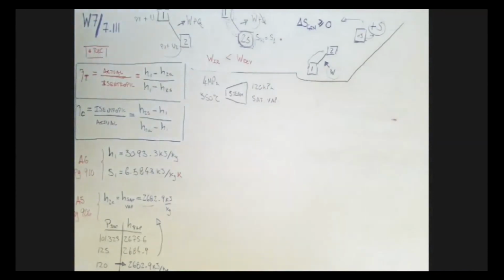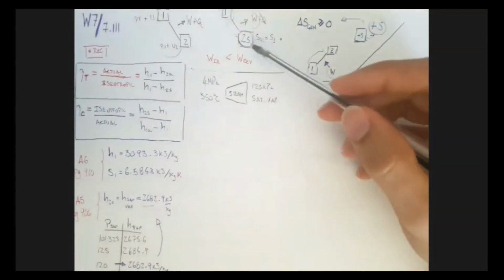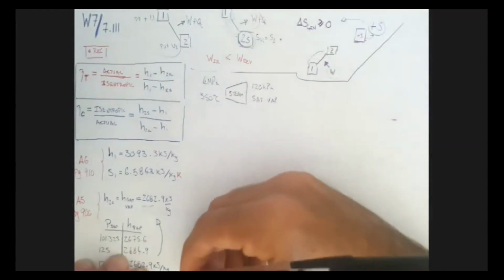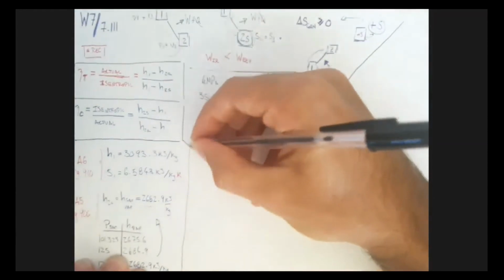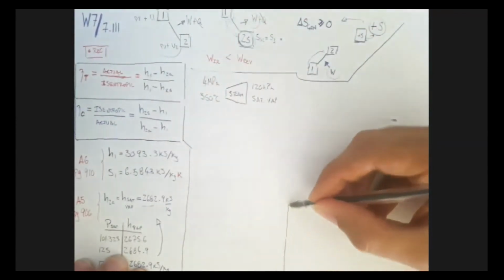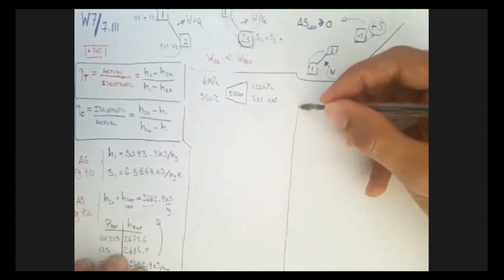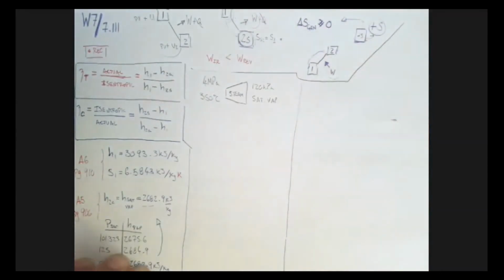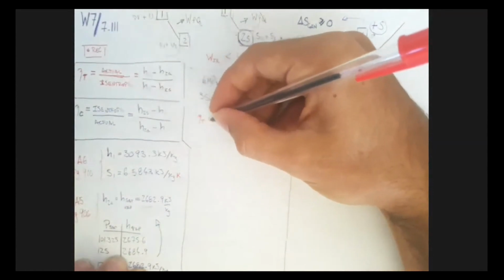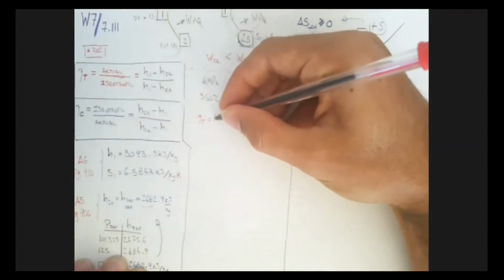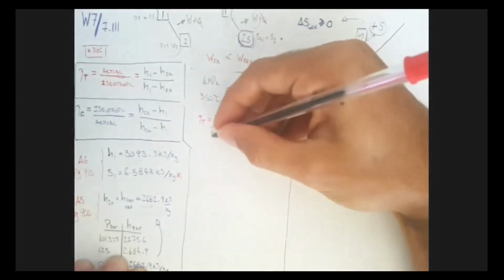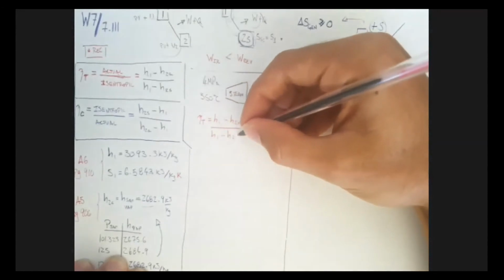Awesome. So now let's define this second state here. We need to find properties for it. We need to find two things to define our state as per usual, right? So let's cross this guy out here. Let's write what we're trying to find, efficiency of the turbine. And we need H1 minus H2A over H1 minus H2S.